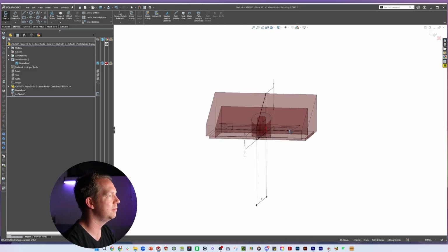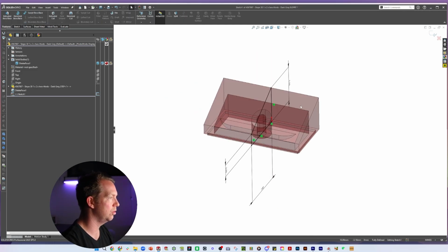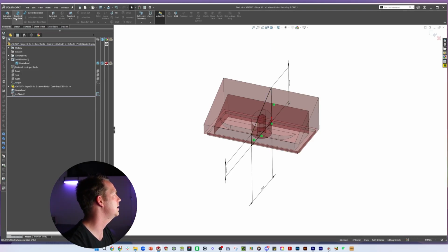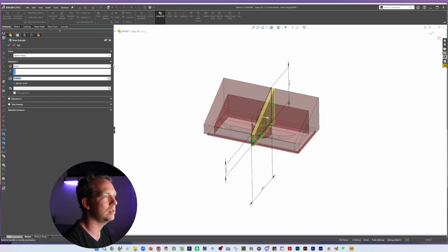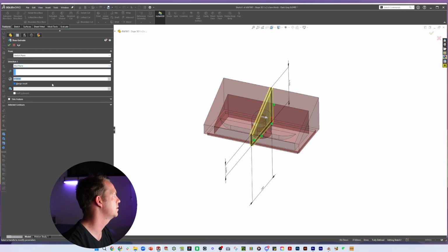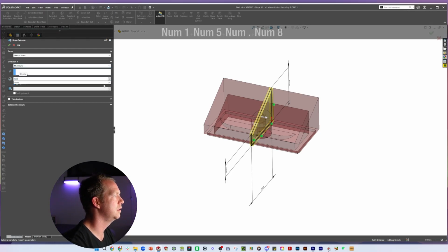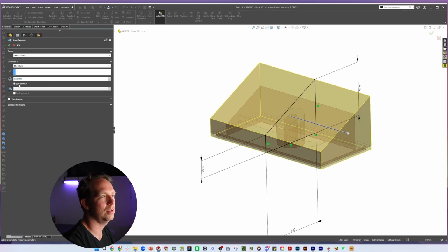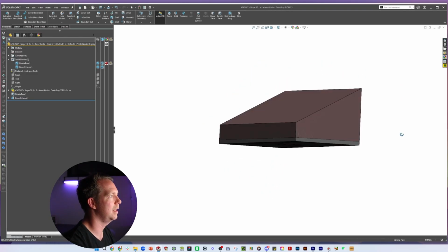It's completely fine. Now, I could do here an extrude going up to surface like this, and the same the other way. But again, that's going to create a relationship to the body that we're going to delete later. So I don't want that. Instead, we should know what the dimension is at this point of the project. 15.8, mid-plane, extrude, and uncheck merge result. Very important. All right, and that is done.